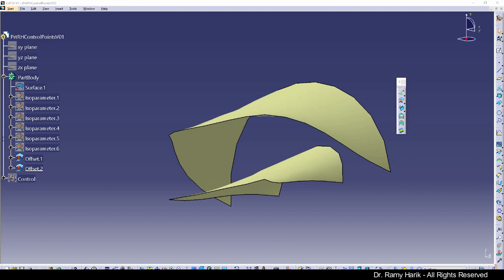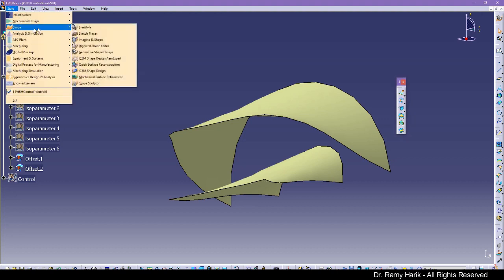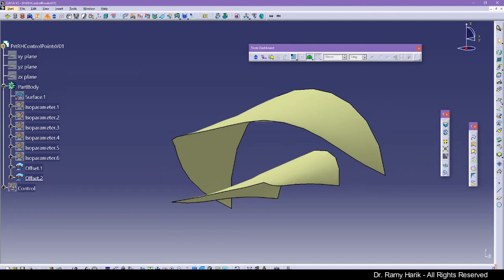If we want to take a look into surface analysis, a lot of the time you need to learn how to move around between these different workbenches depending on what you're doing. But if I click on freestyle, and then select the analysis icon, the analysis buttons are here at the top, and you have several of them.